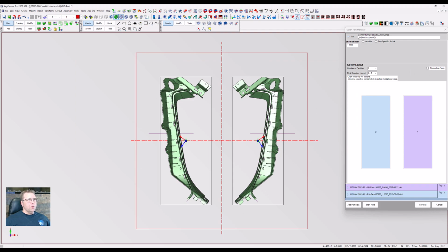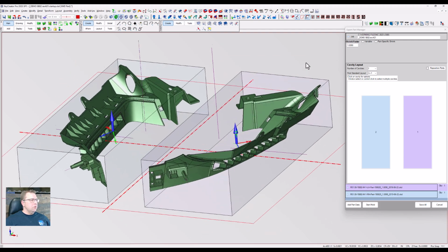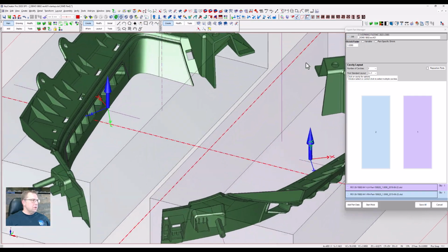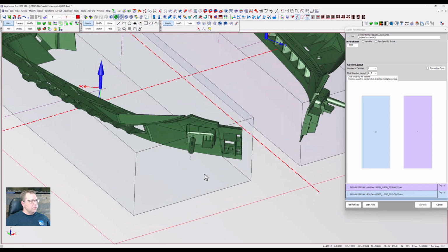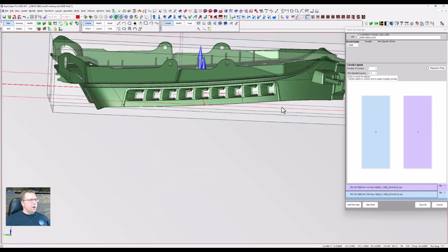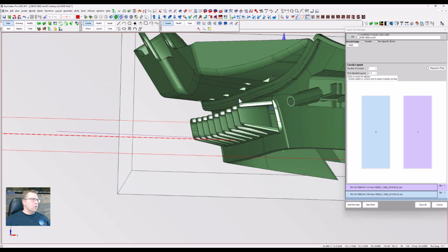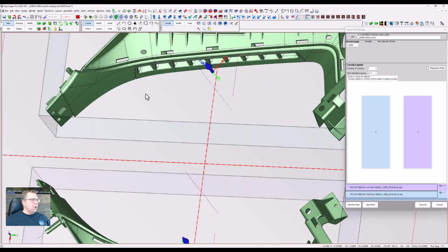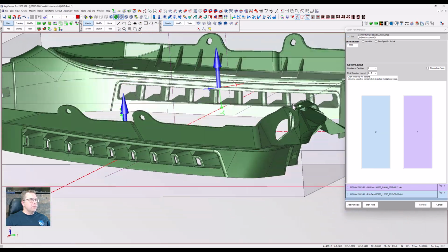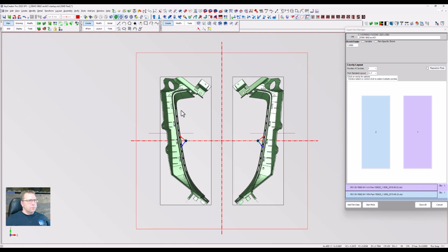So a final quick look at this before we actually start the tool and put some plates around this. Looking at the actions, we know we're going to have a slide over here. We're going to have a large slide underneath here, pulling all the way along the part. And we'll do something like a hook slide in this inner area. All right, simply start mold.